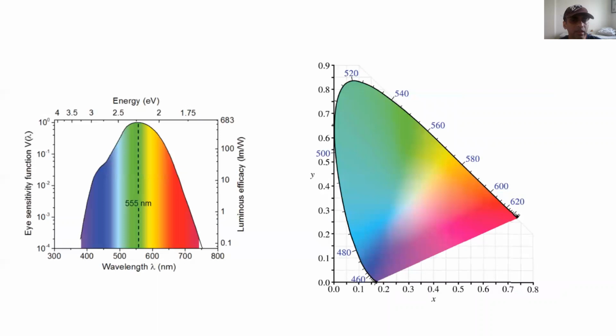In this slide, we basically show the spectrum components for, for example, broad spectrum or white light generation. You have to keep in mind that the indium gallium nitride system, for example, covers the whole range from infrared to ultraviolet through the visible. And varying the material composition can help us achieve some of the components used to get white light emission.